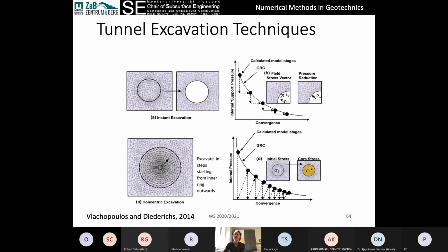First is by modeling our excavation using a pressure. And the initial condition would be that the pressure here, or let's look at it over here, is the same as the in situ stress out here, right? So that would be our initial condition. Everything is in balance, the stresses haven't changed. We have an excavation, but the rock mass is represented by a pressure. And if we slowly reduce that pressure in steps, so we reduce the pressure, calculate the convergence, reduce the pressure, calculate the convergence, we can get an approximate solution to this ground reaction curve.